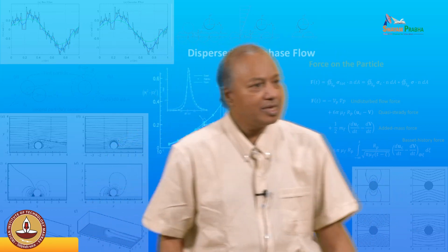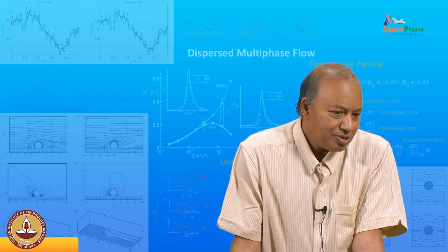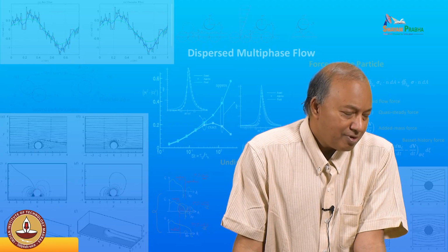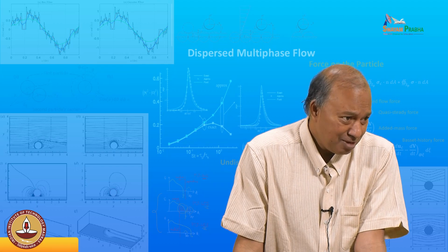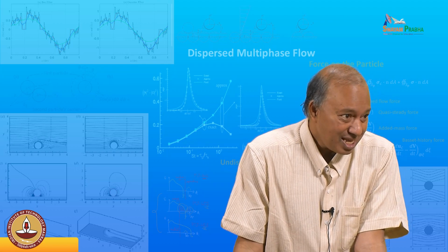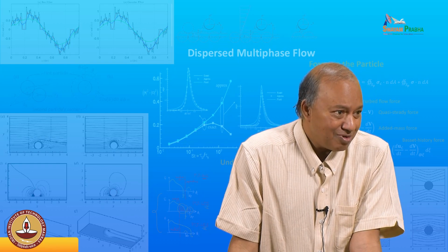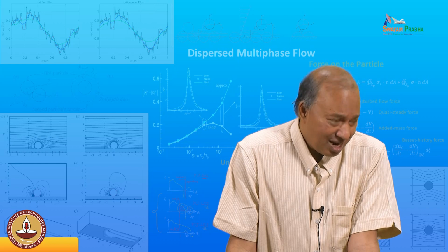So could you repeat about the feedback forces, which you say that depending upon the particle size, the feedback forces will vary. And when these feedback forces will be added to those advection, convection, diffusion, the flow mechanics will be changed. Yes. So sir, can you say that again, which size particles, the larger size particles will have the bigger feedback forces? Yeah, because you see, Stokes drag, even if it's Stokes drag, is proportional to diameter, right? So one big particle will apply a lot of force, feedback force.